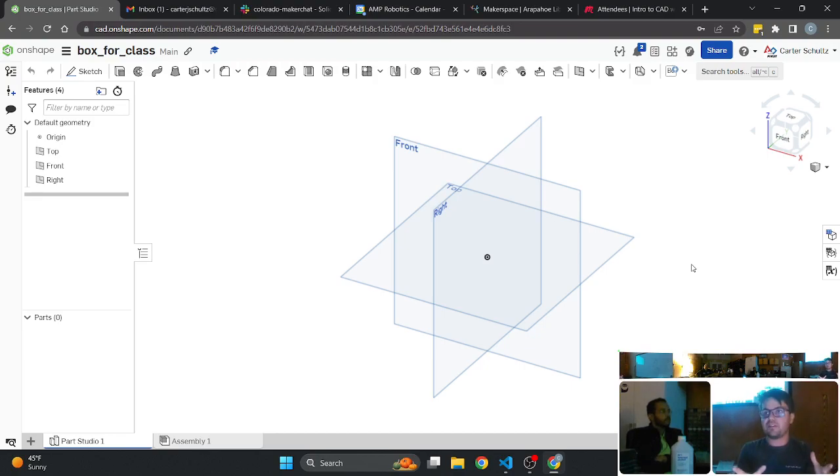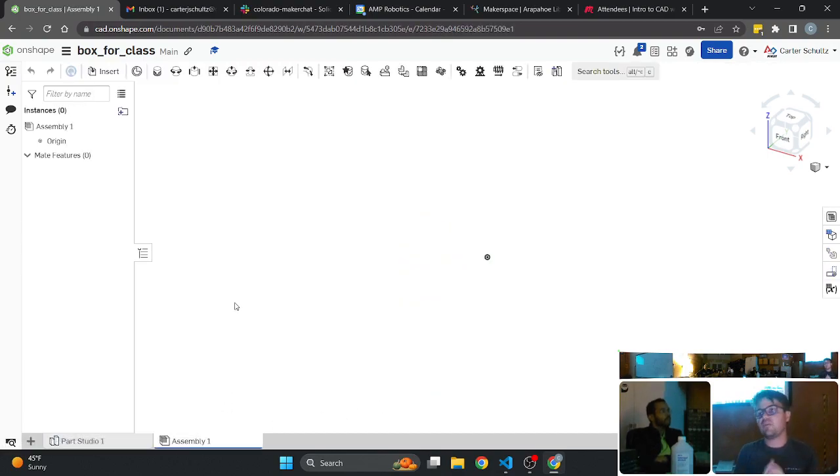But everything in a part studio is static geometry. That's your actual CAD that's generating your parts. You go over to an assembly when you want to make pretty pictures and render things and have things move around. In assemblies, you combine a bunch of parts that you've generated in a part studio together, and you can create things like joints. So generally, in a part studio, you only want one copy of every unique part in your system, and then in the assembly, you go and put everything together in the ways that you want.